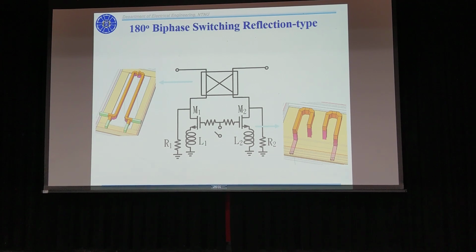In order to increase the output phase shift, we put an inductor in series at the source of the transistor to change the imaginary part of the variable reflection load impedance. To keep balance between the reference state and phase shift state loss, we shunt a resistor to increase the loss at the control voltage so that it can strike a balance.